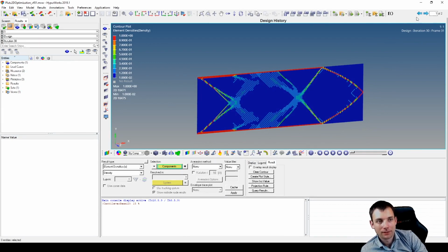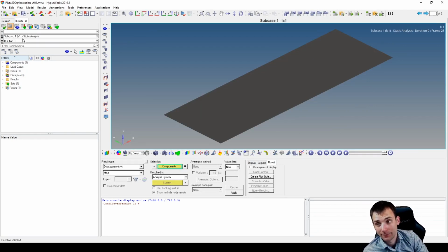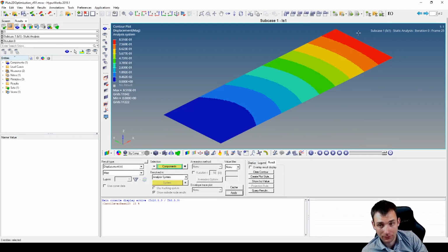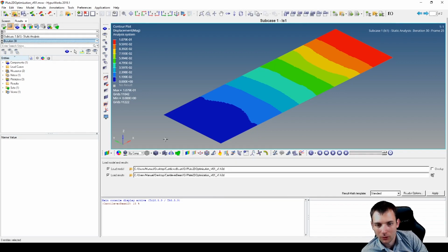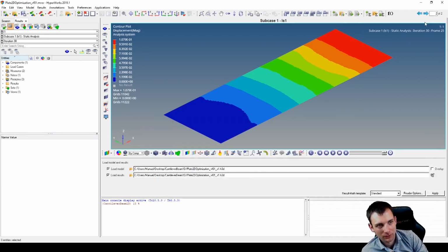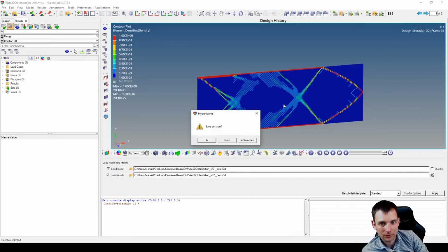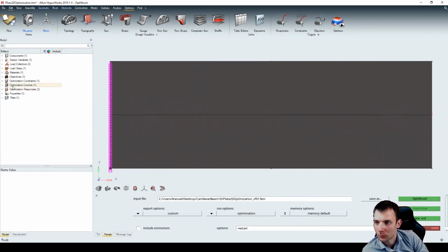And yeah, the second file which is created is the S1 or sx.h3d file, which is a load case, and there you can see the displacement of the initial design and also the last design. But in this case, it's not really the last design because it's opening the first one we calculated, but we did a restart, which we could access here. But as we would have to increase the volumefrac constraint and run it again, let's give it a try one more time.